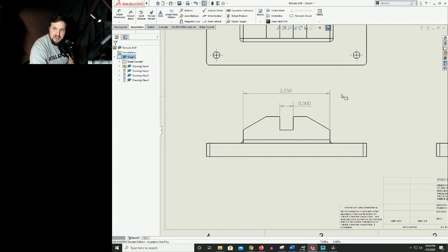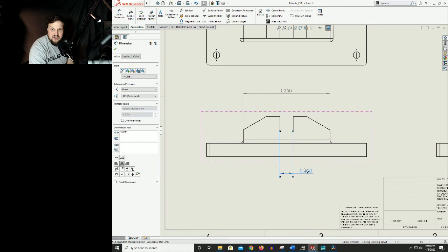Okay? So what I mean there is we've got this 0.5 inches, right? Now, we could put this 0.5 inches down here on the bottom. That would allow us to sneak this guy in here a lot tighter. However, we don't want to do that because right here and here, these extension lines are extending through our model. We do not want that. That kind of gummies up what our overall profile is of our model here. So we want to keep those from going through a model. We want to keep them up here and well separated.